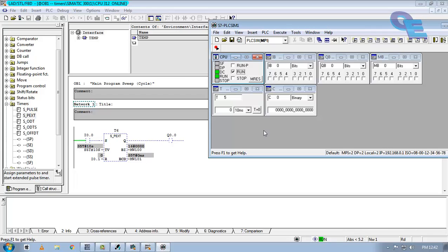Okay, when you trigger the input for a small amount of time, the output is going to be high, and it remains in on state continuously, and it is going to be off after a particular timer value. Okay, I can see I have triggered and released the input, and you can see 4, 3, 2, 1, and the output is off. Okay, in between, if you trigger the reset bit, the timer is going to be off.